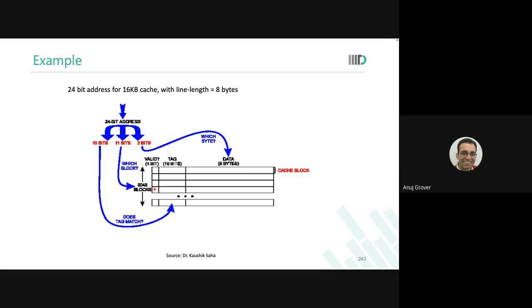As soon as B updates the data, the memory controller of the subsystem will need to update the valid bit. It will at once say that the data in the L2 cache is no longer valid. The data in processor A is also no longer valid.